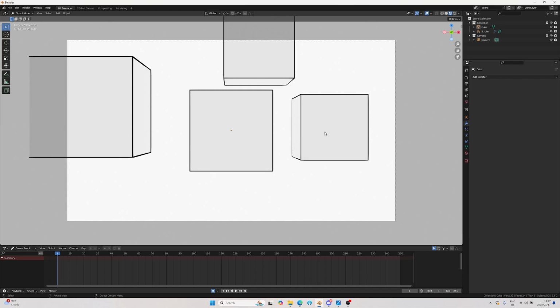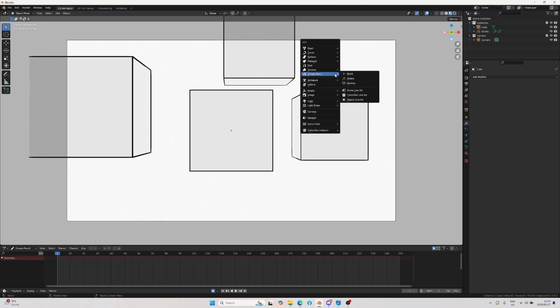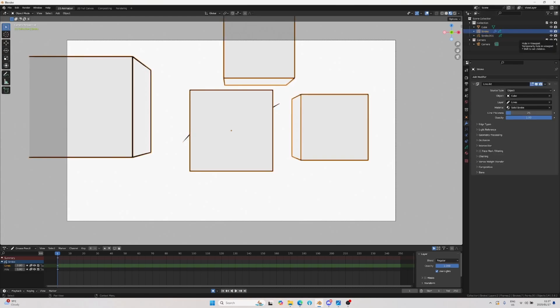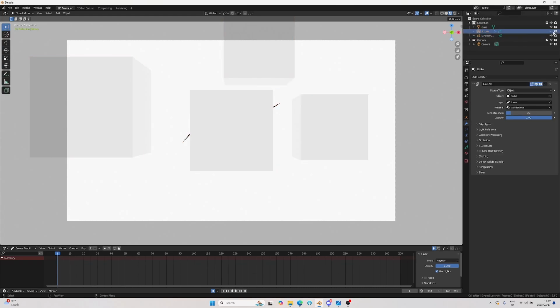And this is where the sort of 2D, 3D integrated workflow really starts to shine, because if I press Shift A and I'm going to just put in a new grease pencil stroke, so strokes can be used to separate different things you're doing with grease pencil, and they're separate objects, so you can switch them off to be rendered or not.